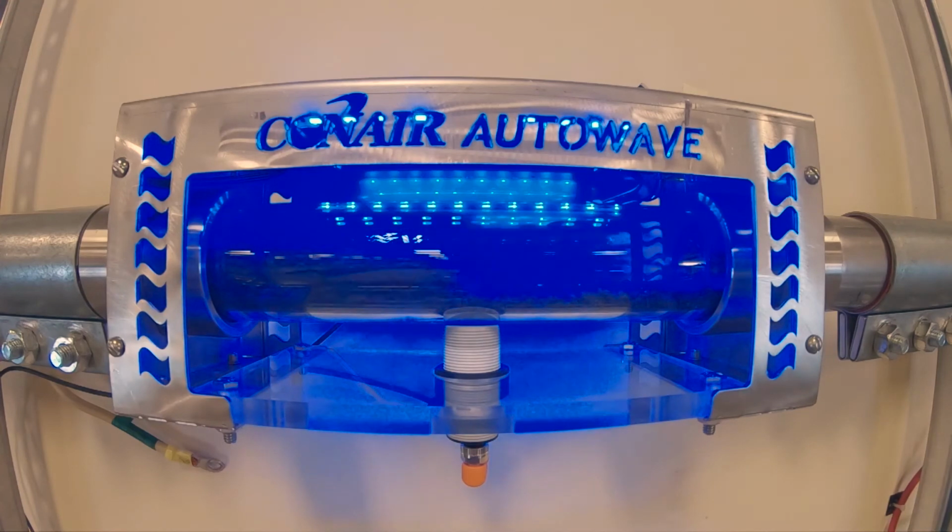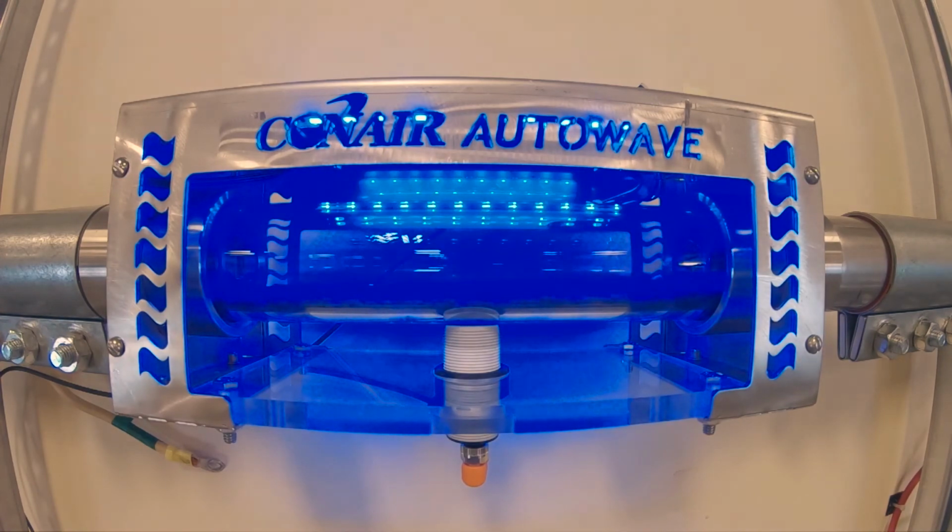Wave pulse technology is going to be for your specialty applications. This is a phase where you're going to have very dense, very thick slugs of material with air pockets in between them to keep that material moving. Where wave stream really could be applied to any pneumatic conveying line today by applying this wave technology to your system.